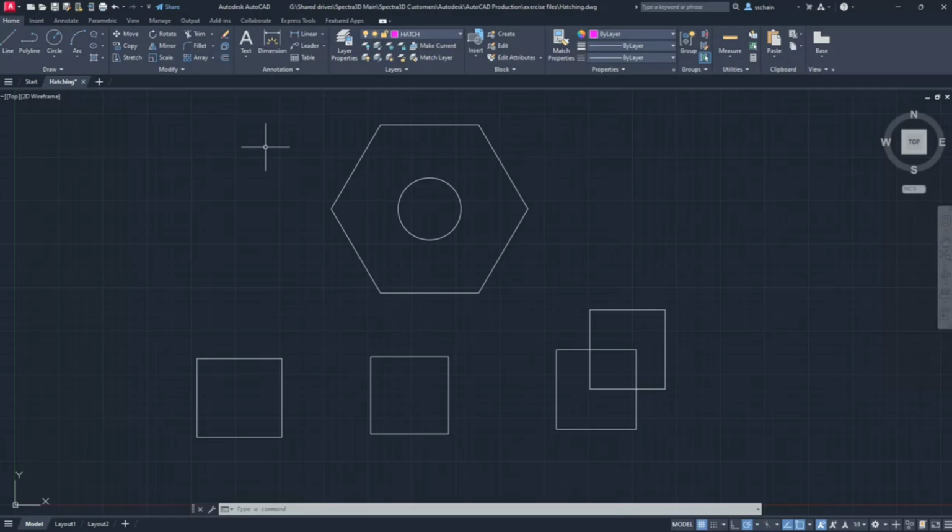However, you can specify the layer on which the hatch objects are created. So, best practice for hatch patterns is to add them on their own layer. That way, you can easily hide hatch patterns by turning off the hatch layer. This drawing includes a layer called Hatch. From the ribbon, Home tab, Layer panel, make sure that the current layer drop-down is set to 0. To add a hatch, from the ribbon, Home tab, Draw panel, click Hatch.